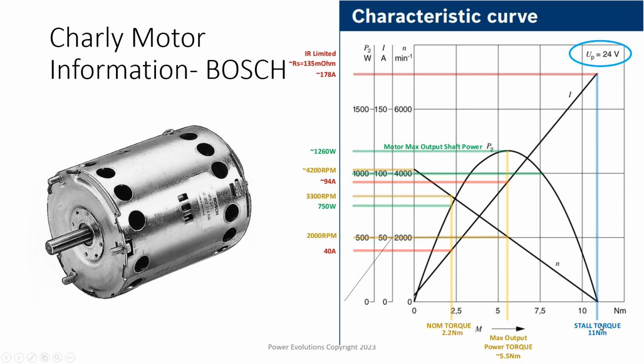That's the point at which the motor is locked, a locked rotor, and that's the maximum current that will go into it. From that you can calculate a rough resistance, which is going to be the brushes plus the windings. I got about 135 milliohms. Obviously you're not going to operate in that region of the motor current-torque curve.